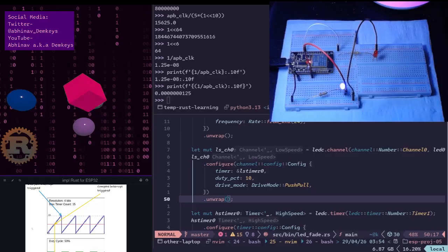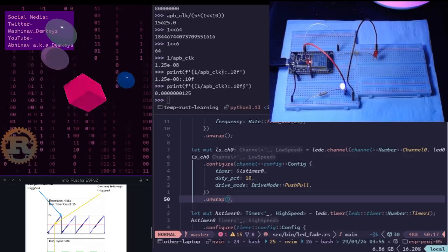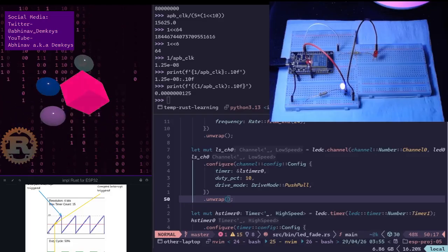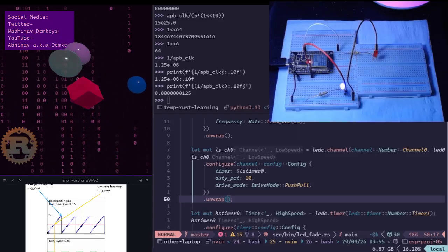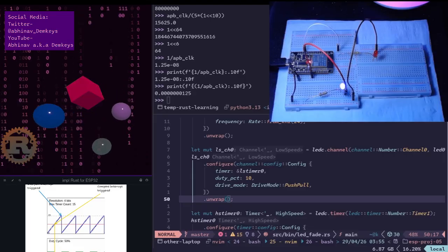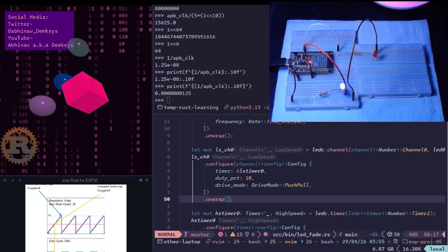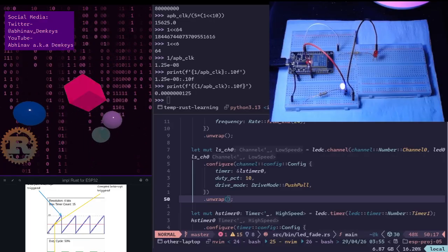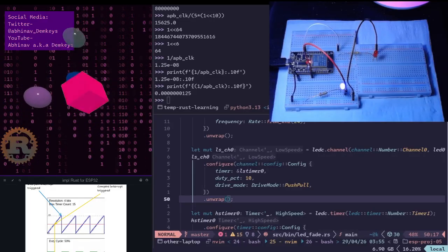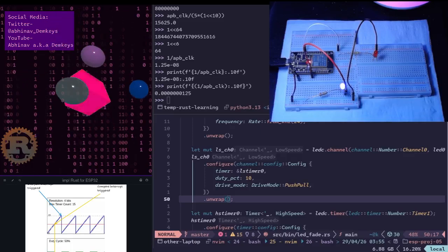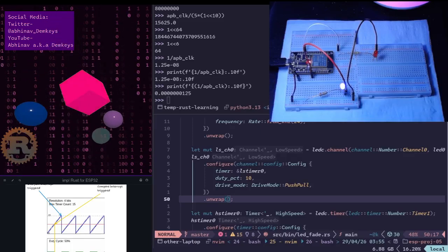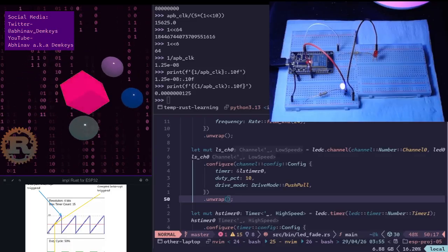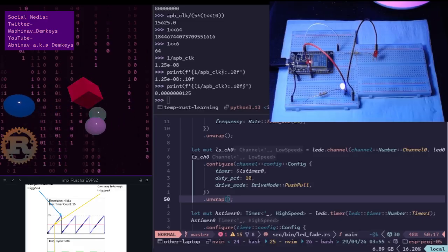So, this counter is essentially what this counter counts. This counter's count is what determines when we have completed one entire period. And okay, so we have our resolution bits register. We get to set whatever the width of it is supposed to be. It can be anything from, I think, 1 bit is a thing. I don't know if 1 bit is a thing, but it can be a certain number of bits up to 20 bits. So you can have up to a 20-bit register.